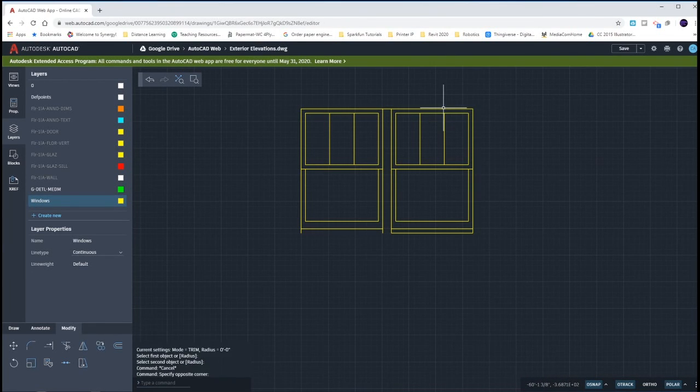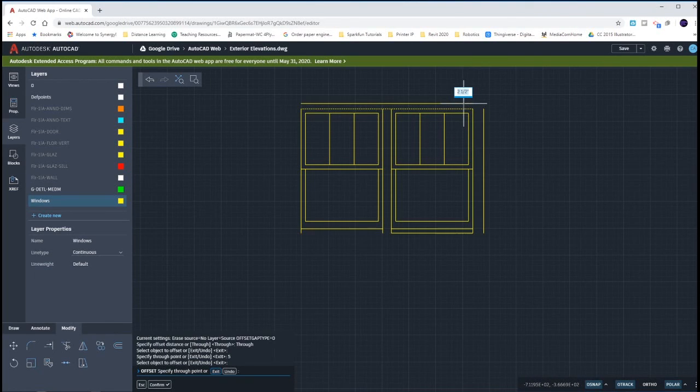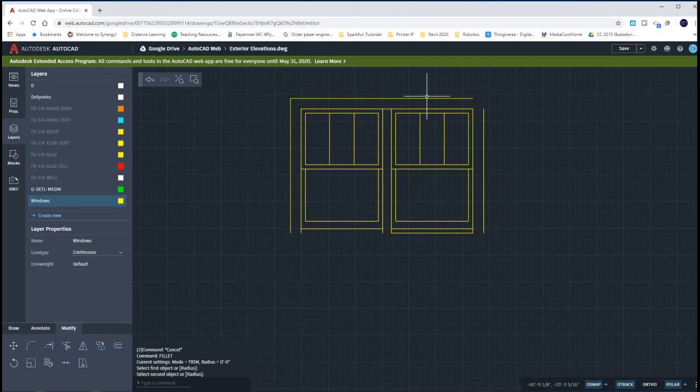That way it's one continuous line going across the top. Now I can do my offsets. So offset outside by 5, offset up by 5, offset over by 5, and then I can do my fillets. So when I fillet here, here, down in the bottom, and from this one all the way over, I can have that go across.